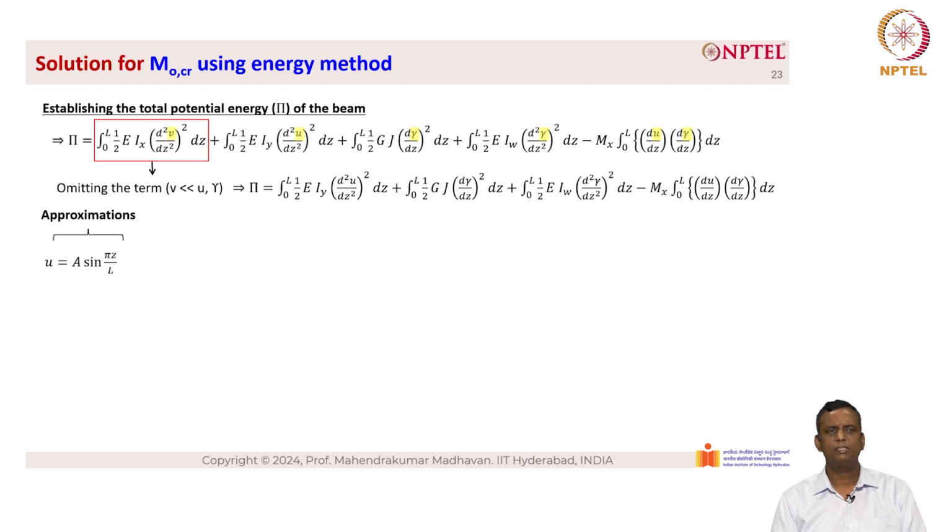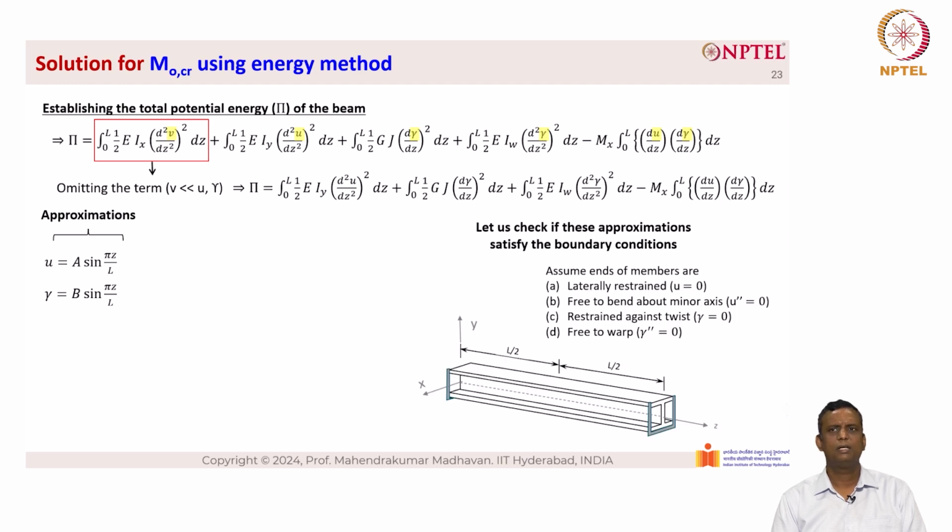So, the deflection function for u equal to A sin(πz/L) and the rotation function γ equal to B sin(πz/L), and both of them lead to approximate solutions. Let us check if these approximations satisfy the boundary conditions.